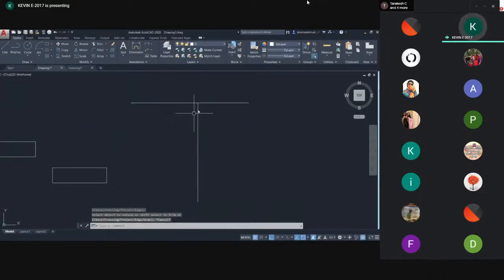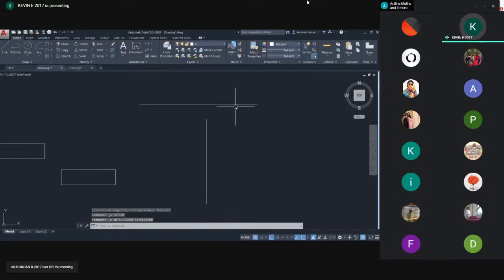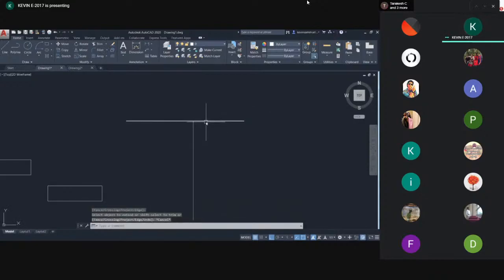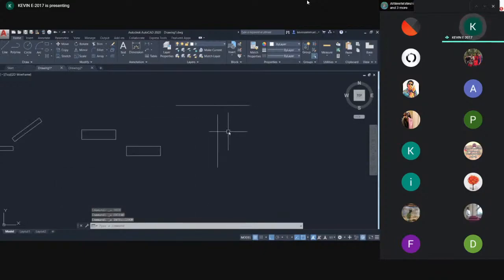So this will be the difference between extend and fillet. If you don't want to select the boundary object also, similarly to trim, you can press extend, and press space twice. Simply the line will find the boundary line itself. So that's what extend is. Like trim, where you press space twice to delete, for extend also the same: EX, enter, again enter. It will just automatically join it. So that's what the draw tools and the modify tools are.